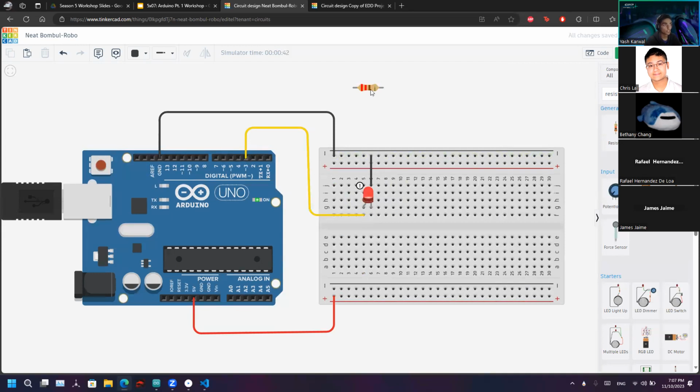So always remember to make sure you have a resistor. In some cases, you're going to need resistors to keep things more manageable in terms of fires and whatnot. So if you were to hook the LED straight from power and ground, it will cause this to explode. There we go. There's way too much current going through the LED than it can handle. So it'll tell you when you made a mistake. You don't want to do that. In real life, it's kind of bad.